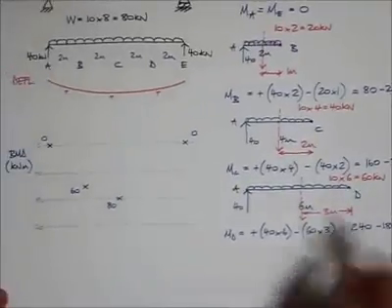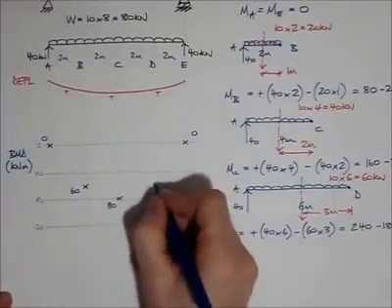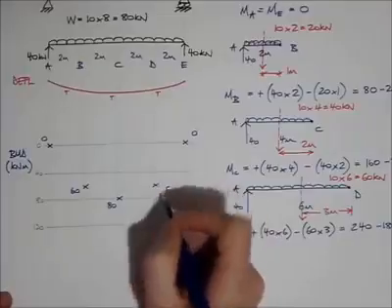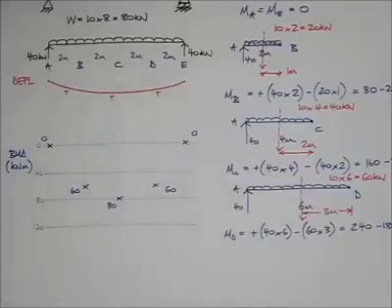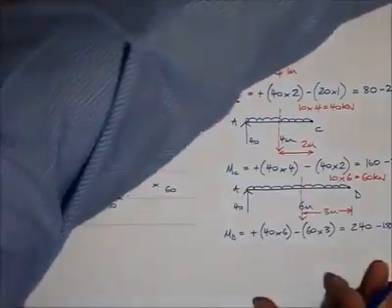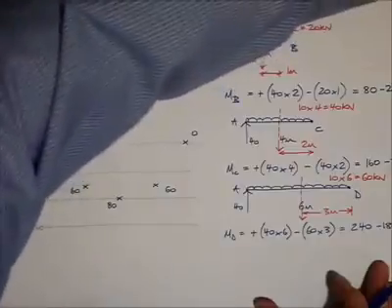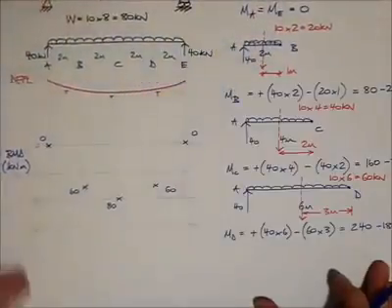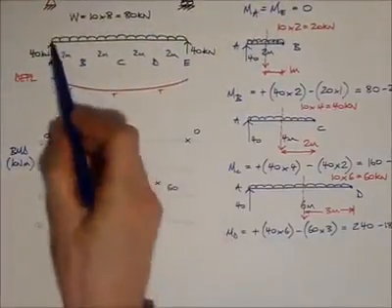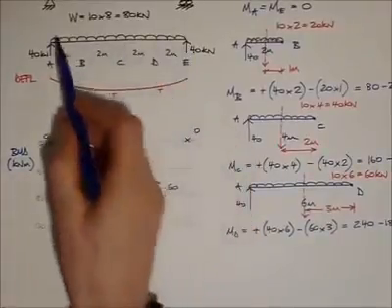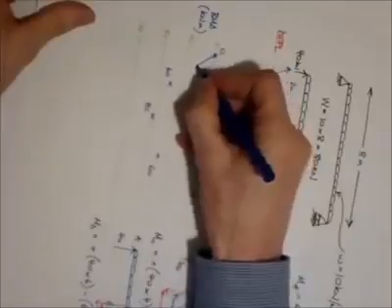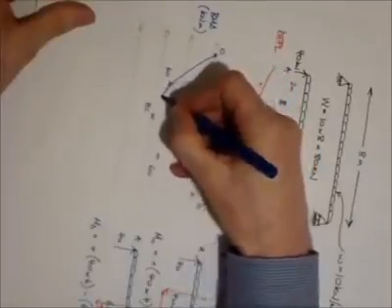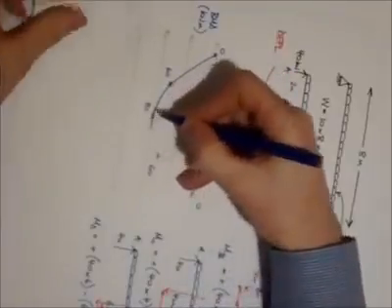So let's add this onto my bending moment diagram now. 60 kilonewton meters. Now I'm going to do my best by turning this around to draw a smooth curve joining up these points, and it's going to be a curve because I've got a UDL along the length of the beam. So here's my curve, my best attempt at a curve. Not bad so far.